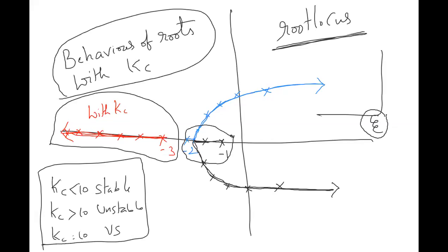See, root locus analysis is something which I do for a characteristic equation. You can take a simple equation. Let's say I will take three systems in series: 1/(s+1), 1/(s+2), 1/(s+3), and put a controller Kc and derive the characteristic equation, and then you can find which one is going to be stable and which one is going to be unstable.